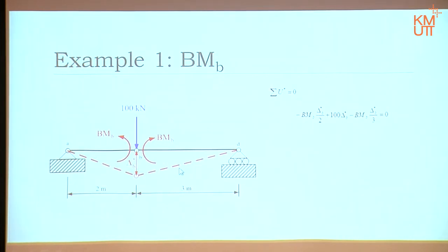However, that theta is equal to delta B divided by 3, that term. Okay? The moment itself is going clockwise, BD going anti-clockwise. The work done is negative here. There we are. Because of the way I set it up, every term has delta B, so I can take delta B outside into that term.